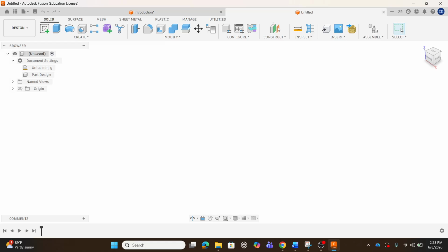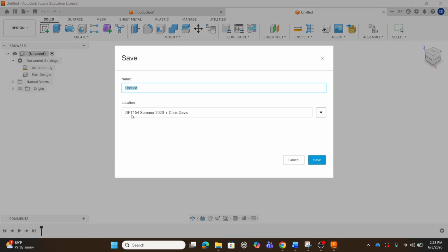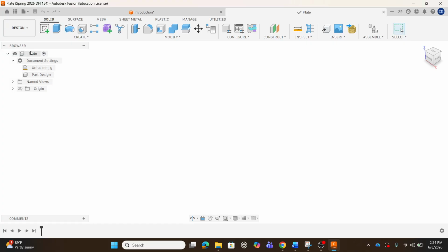So this one, remember, first step, we save. This number one, biggest, most important thing is to hit save. Make sure your units are right. We're in millimeters, that's good. We're a part design, that's good. I come up here to the top, I hit the save icon. Make sure that I'm in the DFT154 summer folder, and your name should appear right here. And then we're going to call this one plate. So we'll type it in, hit save. Notice the top now says plate.